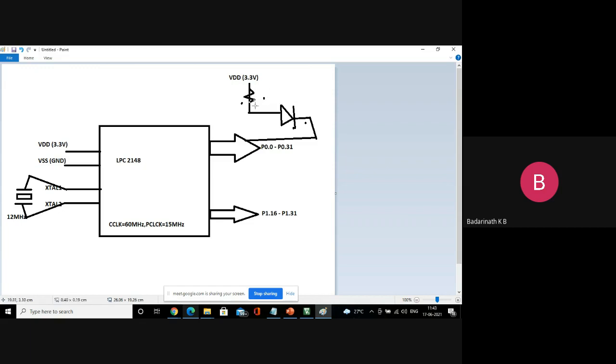So now I've introduced a resistor also. My logic is ready. So this is how you start building the boards whenever you have a microcontroller with you. The only thing is there is a pin called reset available. That also has to be handled. That I'll discuss probably in the next class, because if you don't control the reset pin properly, it will not work properly.